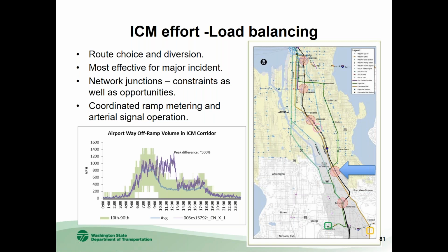And it worked out very well because the peak period on I-5 is almost like a solid peak. From 6 in the morning until 6 in the evening, you have a solid line of traffic, whereas all of the parallel routes have a traditional morning and afternoon peak. So during the off-peak, there's capacity on the arterial first to send traffic over.